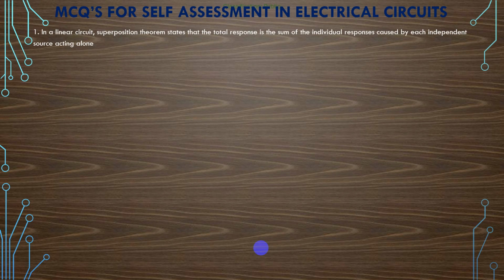Now see the complete circuit with only one voltage source, what you assumed. Then solve the complete circuit, the branch resistances becoming an equivalent resistance. Then voltage divided by that resistance, we will get the current. Now come back to the different branches. What is the current and what is the voltage?